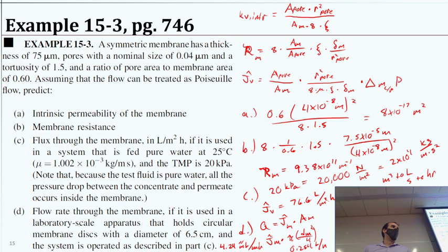So, yeah. Like, let's say you're trying to measure how much fouling you're getting. Would you compare your real observed flow rate to like theoretical or your initial? Yeah, that's an excellent question. So if we want to determine fouling, how are we doing that? It actually depends a little bit on the way you're operating the membrane.